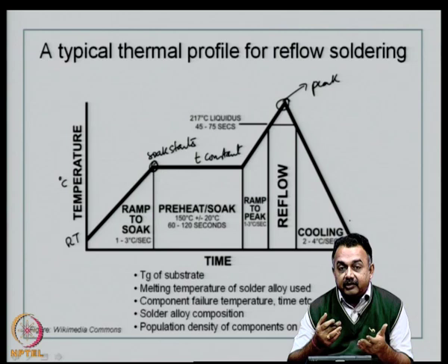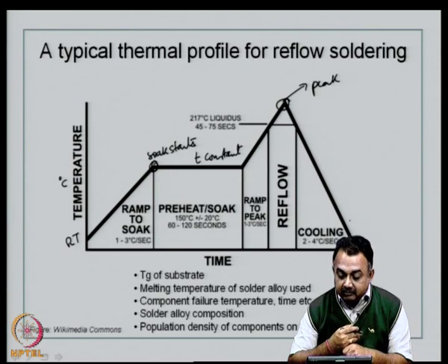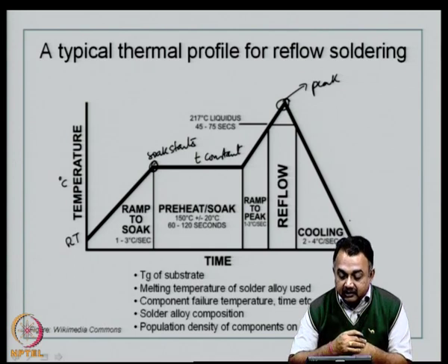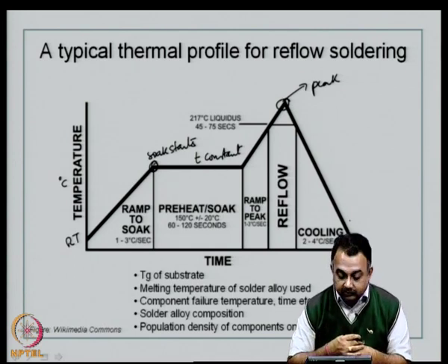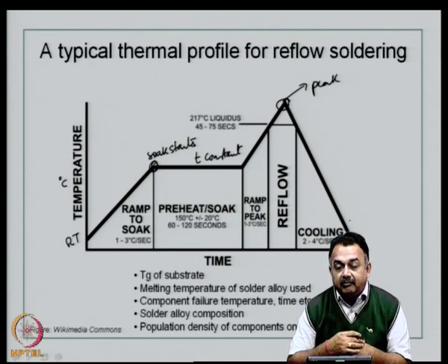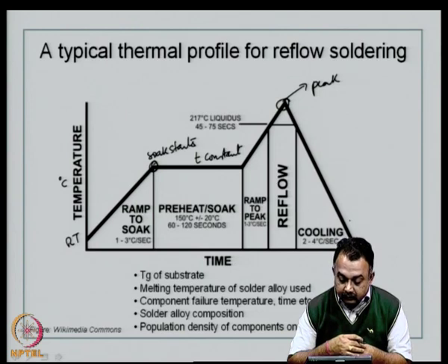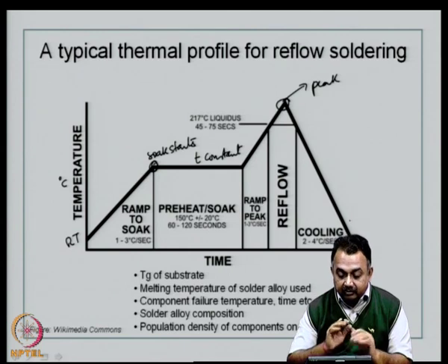In some cases, if it is a very reliable solder paste material and if you are very sure of the reflow process being done at a smaller window, let us say plus minus 2 degrees centigrade, then this kind of profile can be used. But if you are using materials which you have not used before, or if it is having low activated paste, then you want to keep more residence time at the peak reflow. So, these are the two basic thermal profiles that you can see in literature today, and you can fine tune it or change it according to your requirement.